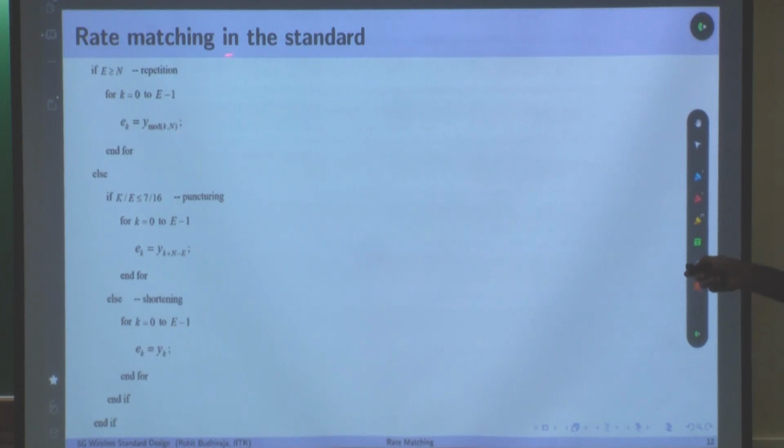This is the repetition, and this is the rate matcher for the PDCCH block. In the PDCCH, none of this is required because you consistently drop bits from the beginning. So a separate rate matcher has to be designed for this, because the polar encoder has different characteristics than the LDPC encoder. These are two different characteristics of a polar encoder which are not there for the LDPC encoder.